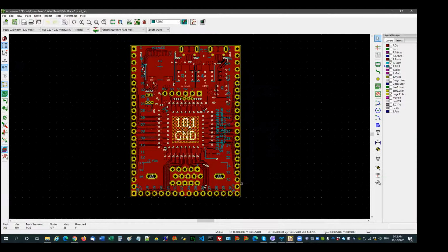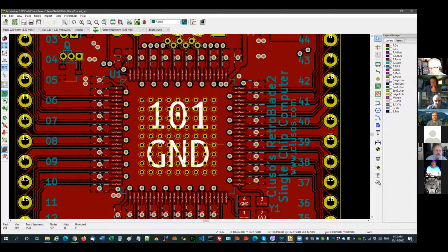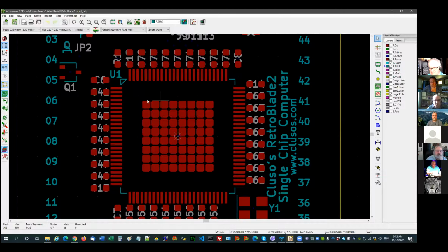Oh, yes. Okay. So that's the chip. You can see all the holes. Now, what I did, I took an existing KiCad footprint which had fewer holes underneath the chip because the center pad was smaller, and I just expanded them out and did a couple of tweaks. So if I turn that layer off, now you can see this is the actual silk screen layer. You can see they're little pads because you don't put a big pad on the bottom of your board.